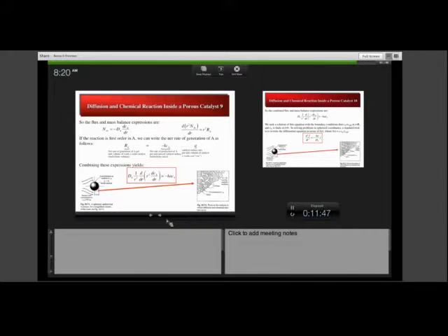And so one of the things you can see happening is that you give up, in this approach, a detailed view of the concentration inside the gas phase throughout the catalyst particle. And in that gas phase, the molecular properties of diffusion and so forth do apply. It's the same. The diffusion coefficient of one species and another is not different inside the catalyst particle than outside the catalyst particle in a molecular sense.